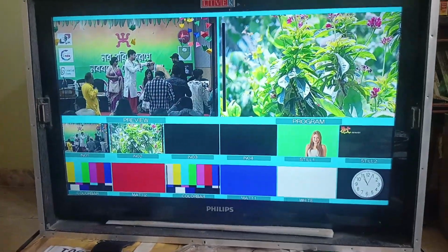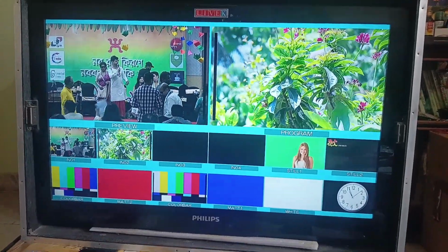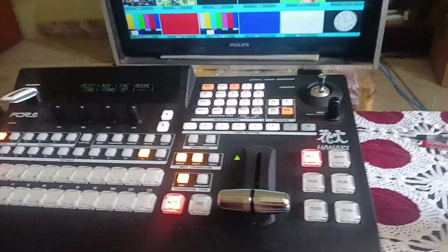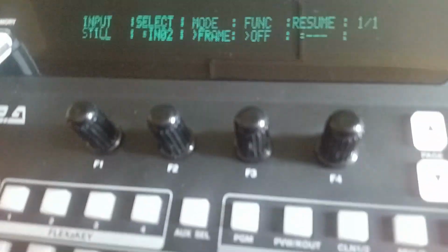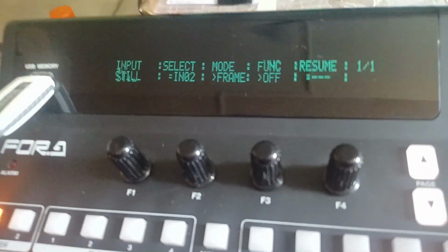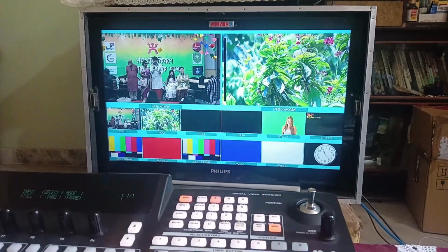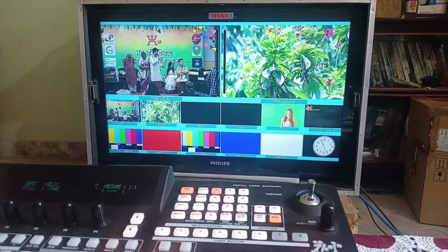Sometimes operators do it without knowing the matter, and they think the problem is in their video cable, maybe the BNC cable, output, camera, or playback device, but no, everything is okay. Only the input froze due to these operations. So in this way you can clear it.